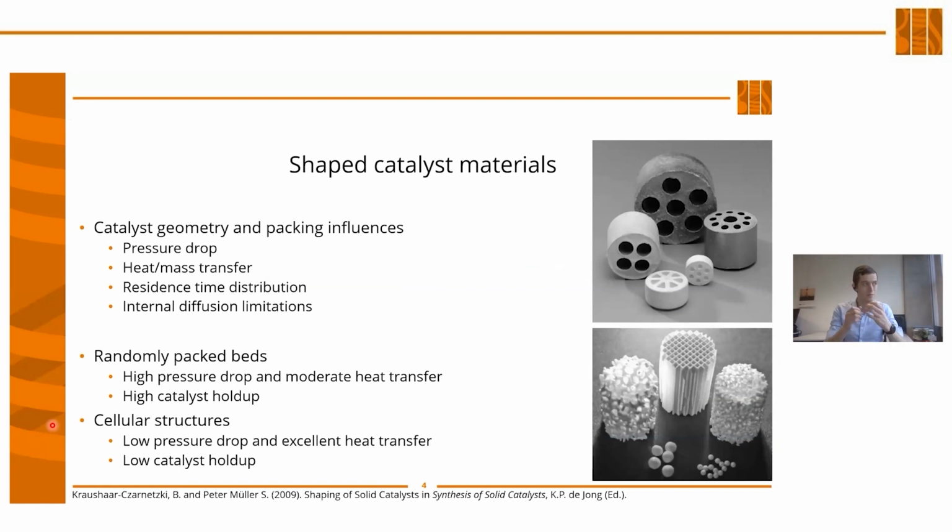So being able to have that gas contact the walls as much as possible is critical to having good heat transfer and the temperature that we want everywhere in the reactor. So the catalyst geometry and the packing, the way that it's laid about, tells us how the gas will flow around and how much it will contact the wall. So this is super critical in ensuring good heat transfer.